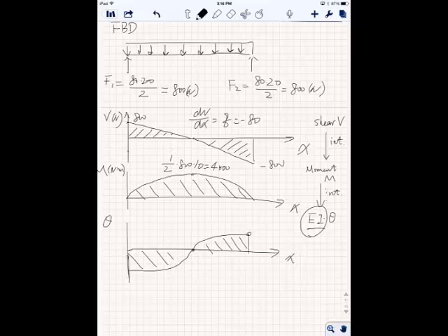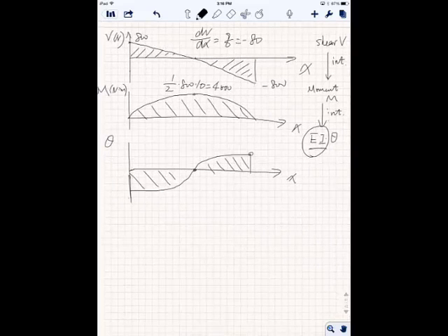Why is that? Because when you have a case like this, what you're seeing over here is an equivalent load in the center, and you have two supporting forces on left and right. Of course this is equivalent to a concentrated force right in the center, therefore it looks like this, right? Slope, what's the measure of slope? dy divided by dx, right?